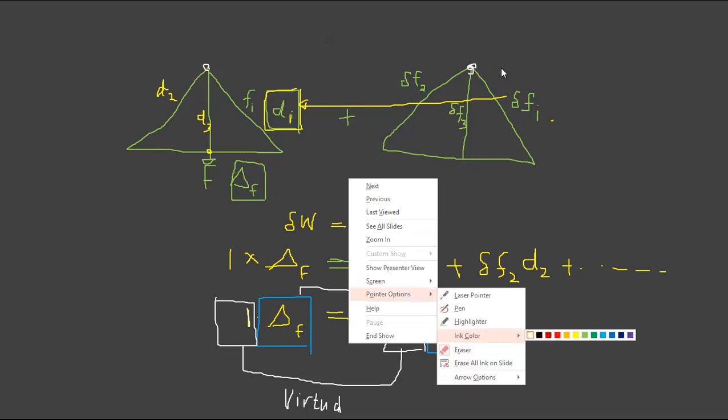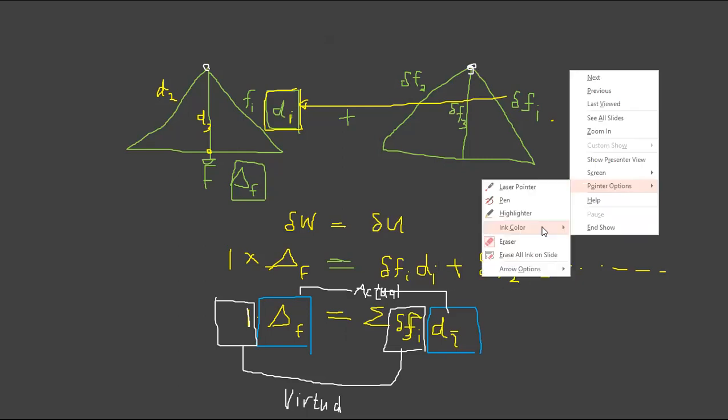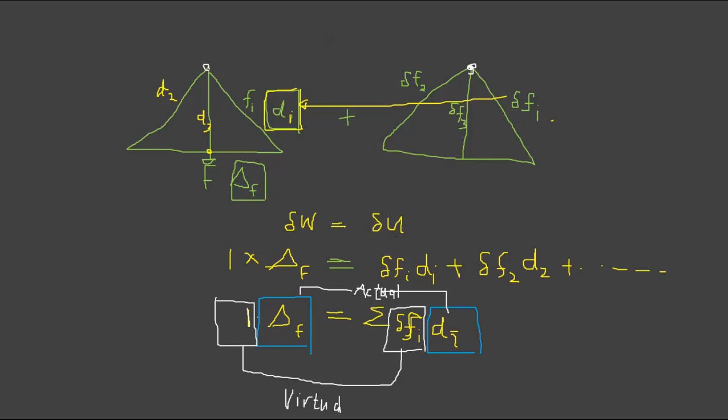And you have to apply where you need the deflection and in which direction, and in that direction you have to apply a unit load. That's it, right? And then calculate the member forces. So then again this equation: virtual force, and a virtual work added externally, multiplied by the original displacement of that point, right?